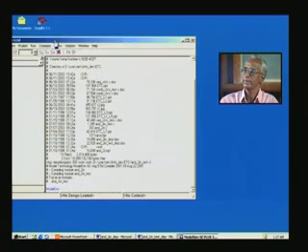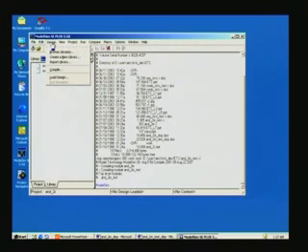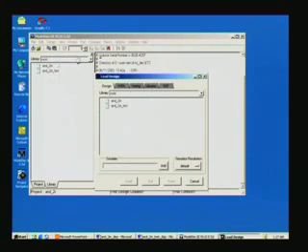So the next step is, you have now compiled your test bench as well as the design. Now it is high time that you load it into the simulator. So our aim is to see the timing diagram as such, and we will be seeing that shortly. So before that, what we have to do is load the design that you have compiled. So again use design, and after compile you see a load design. Just click on this. The whole thing is menu driven. You have only to note what I have been saying for different things, and we may be summarizing all